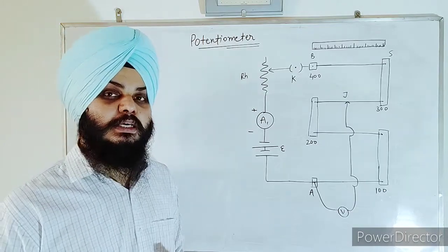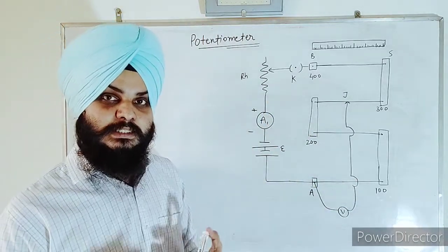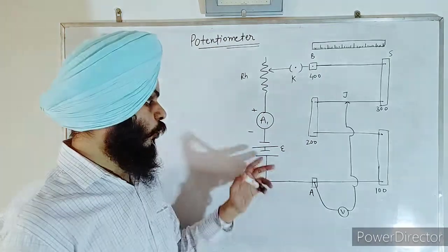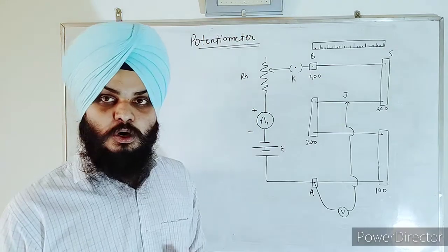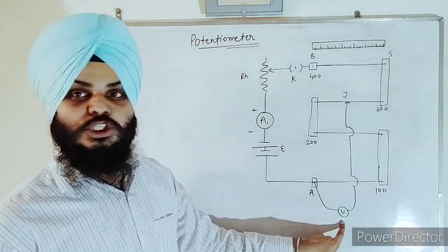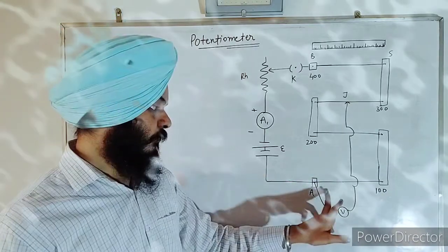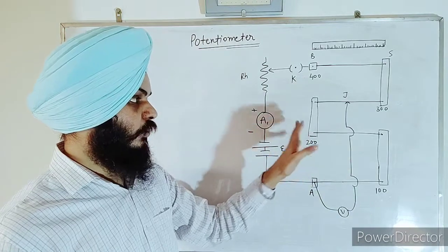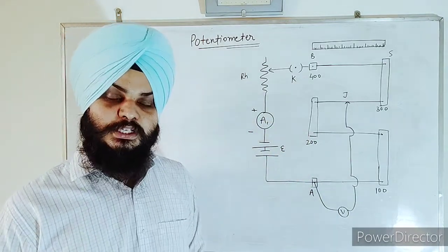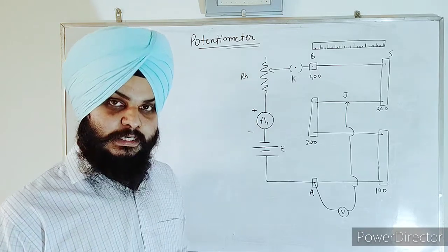Ultimately, on increasing the length, we may find some point at which the whole of the potential difference applied by the battery is dropped and you get a 0 volt voltmeter reading. That means we can get the resistance from that much length of the wire for which the potential drop is the same as provided by the battery.